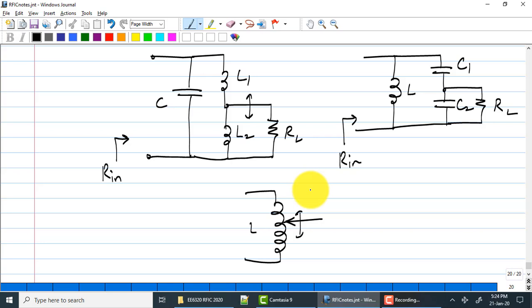The way we started looking at matches, you started dealing with circuits that are non-ideal series or parallel resonant networks, as in you don't have a pure series or a pure parallel, you had something which was a hybrid. We try to convert to either a full series or a full parallel. Let's start with the tapped inductor. How will you convert this into a pure series or parallel network? Any ideas?